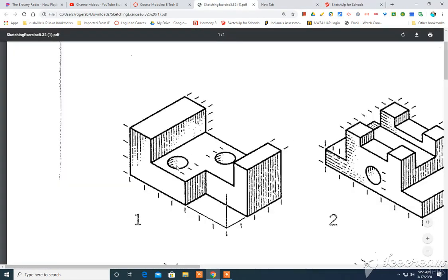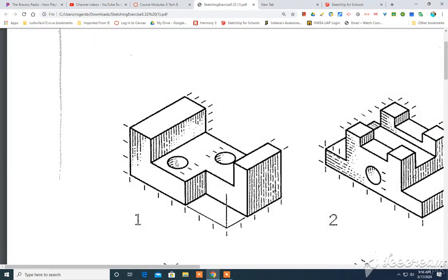Well, looking at the holes here, from our grid sketch, you remember we said this distance here was 1/4 of an inch. And then we need to know the hole center here, because that's how we form the holes with the modeler. If you remember my discussion about the radius versus diameter, to find the hole center I have to know the radius of this circle right here. I see that the diameter is 1/2 inch, so the radius would be half of that, which is 1/4 of an inch.